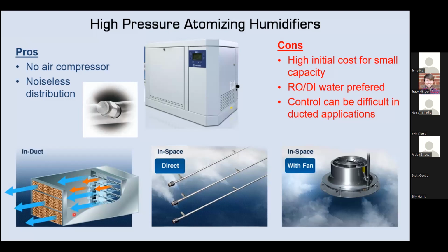You do need RO water. It says preferred, but it's required, because the nozzles are going to precipitate calcium, and what'll happen there is you'll clog them, or you spray dust in the space.